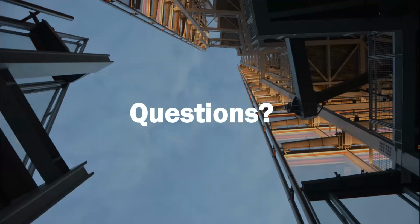Okay, that's a good question. A very common question. The short answer is still to this day, unfortunately, it's not possible. You cannot have line types in Revit with letters or characters in them as you can in AutoCAD. That's one that comes up all the time, particularly for hydraulic services. It's a workaround still to this day. There are some things you can do, but there's no out of the box way to have those character based or letter based line styles in Revit. You can add tags and things to it. There are some workarounds, but they're not ideal.